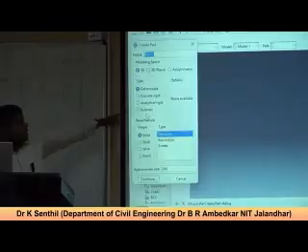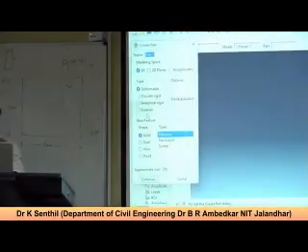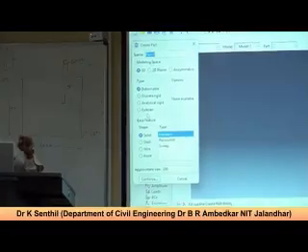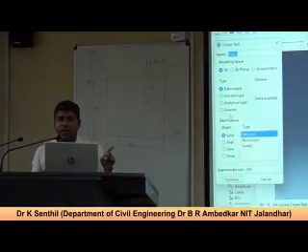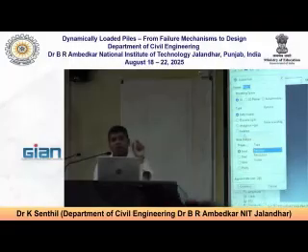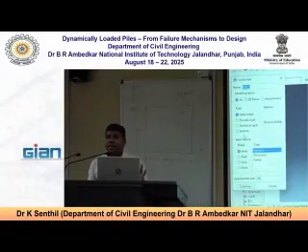But if you see here, it's specifically mentioned as the Eulerian model. If you want to do the Lagrangian analysis, you can define it in the step module as well as during meshing. During meshing, there is an option, standard. That standard shows it is a Lagrangian.